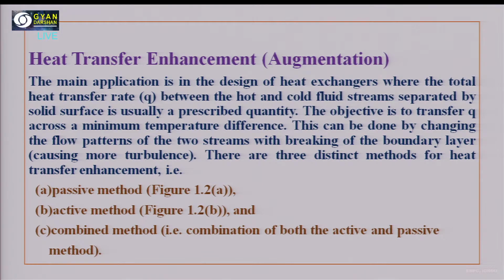Then how we can enhance the heat transfer which is taking place in our heat exchangers, or we can also use the term augmentation in this case. So the main application is in the design of heat exchangers, where the total heat transfer rate, given by small q, between the hot and cold fluid streams separated by a solid surface is usually a prescribed quantity. The objective is to transfer q across a minimum temperature difference.